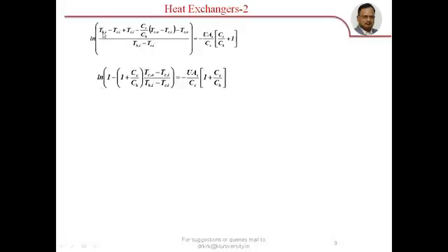What we will do is, we got THI minus TCI and THI minus TCI. Separate it. You will get 1 minus of, and in this take out the common TCI term and TCO term also. You will get 1 plus CC by CH into TCO minus TCI by THI minus TCI, which is equal to the right hand term.